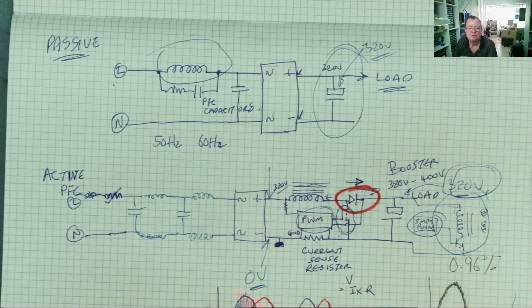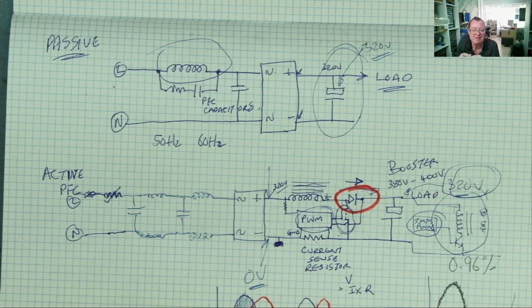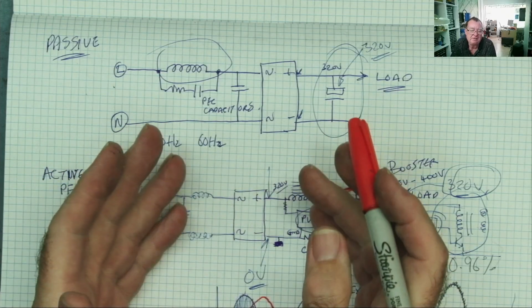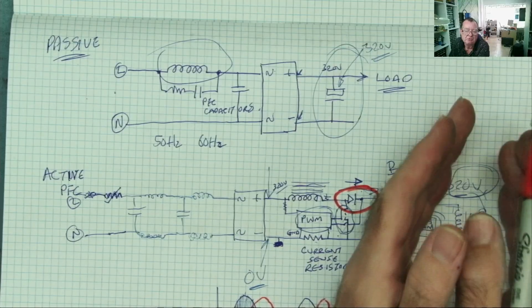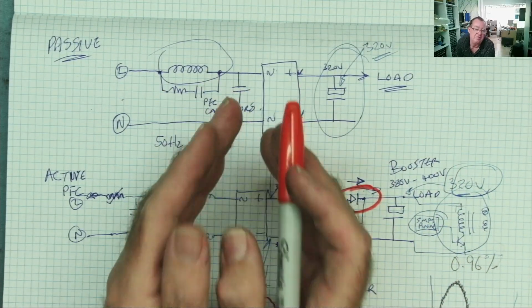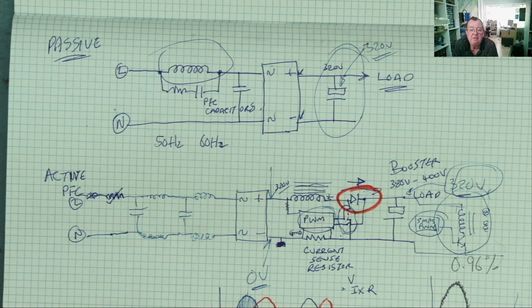That little beggar is just waiting for you, because you weren't prepared. It still has lots of voltage to give you a good zap. So with PFC, remember, you cannot check if it's a dangerous voltage here by measuring there. That's important, guys, okay? So that's probably all you need to know, really, about PFC.